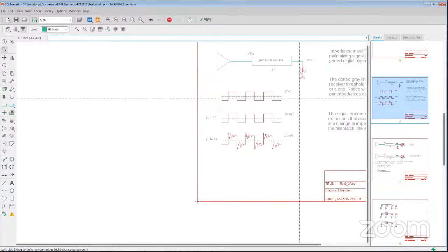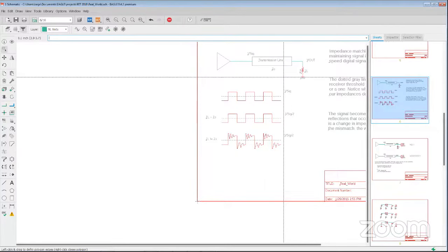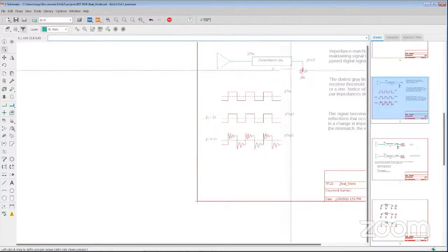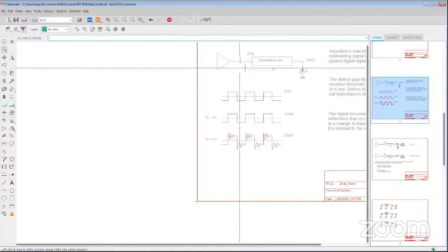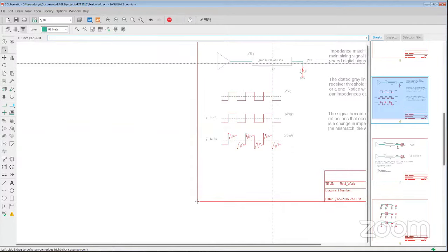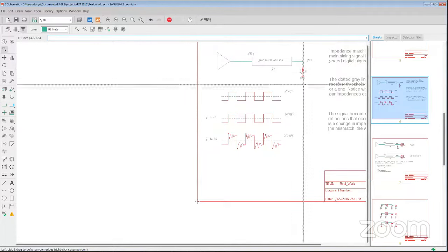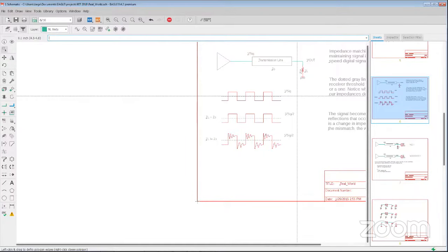But when you're dealing with maximum power transfer, which is more critical because you want to maintain the quality of the signal, you have to, in your mind, get used to the idea that the voltage that's arriving at V out is going to end up being half of the voltage that you put in. And the reason for that is that you have matched impedances. The impedance of the transmission line and the impedance of your load, if they're matched, it's basically a really simple voltage divider with the two resistors being the same. Hence, your output voltage is V over 2.